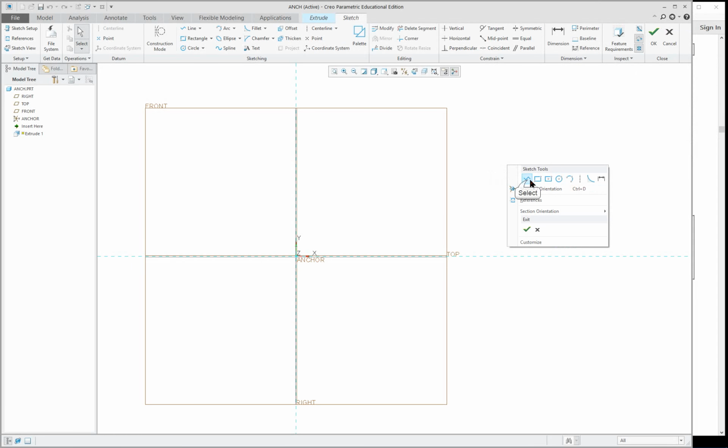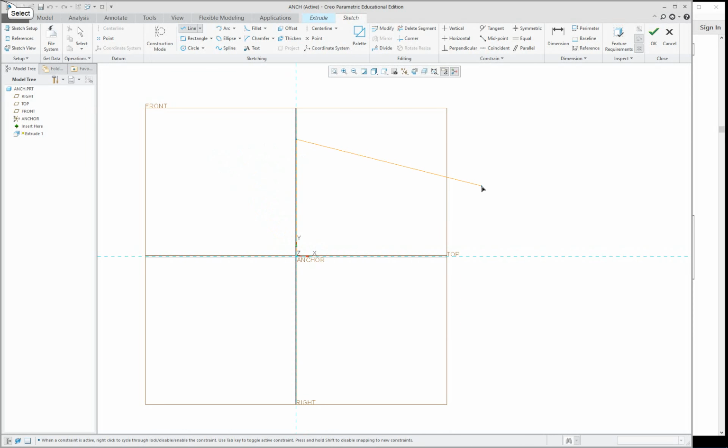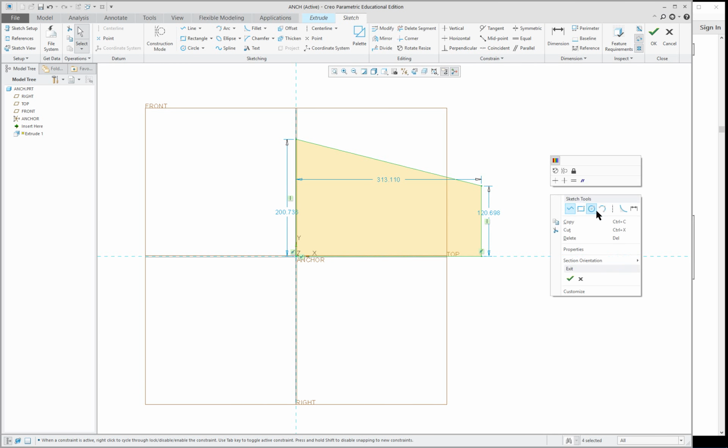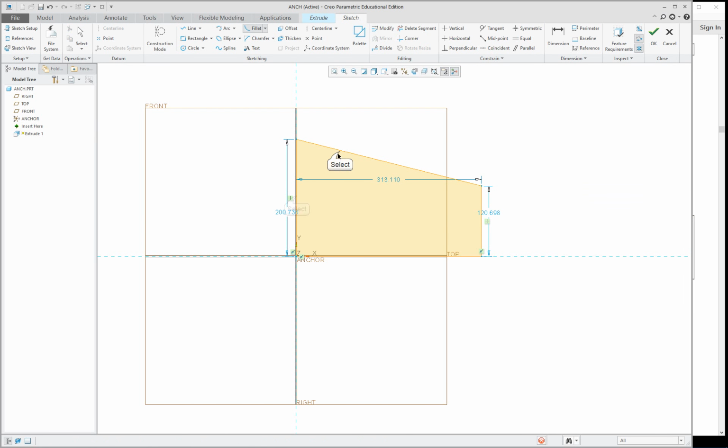So we are going to simply use the line tool and create 4 lines. I always pull mine off when I'm done. Let's see if I got that right. No, it looks like I keep hitting my middle mouse button accidentally. So I really want to finish this, then I pull this off and click my middle mouse button twice. And right mouse button, we are going to use our fillet and connect one line to another. Wherever you click, that's pretty much where it's going to put the radius value.